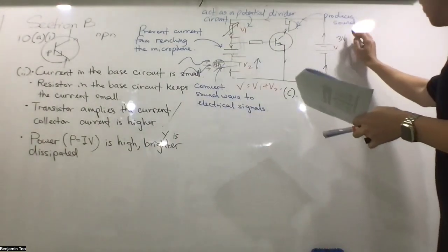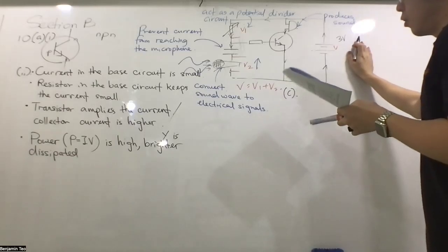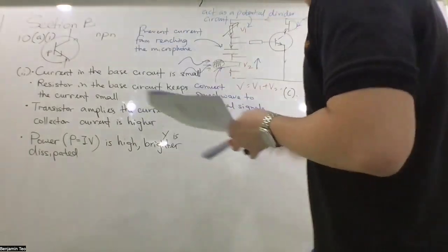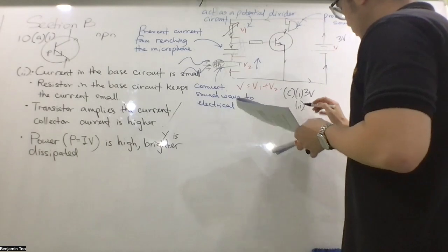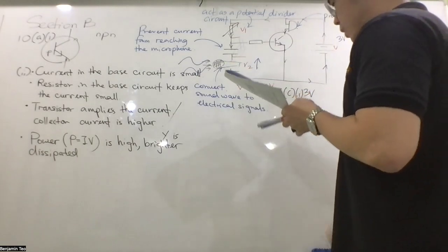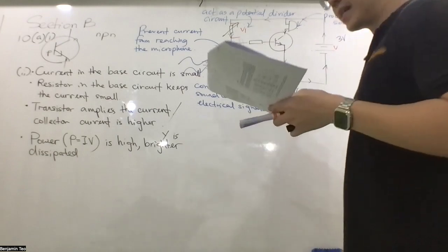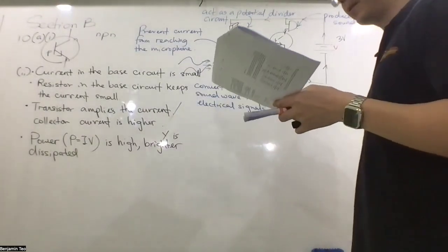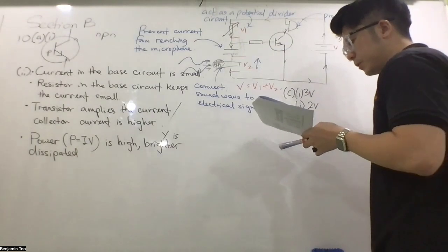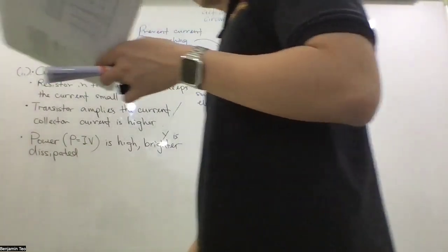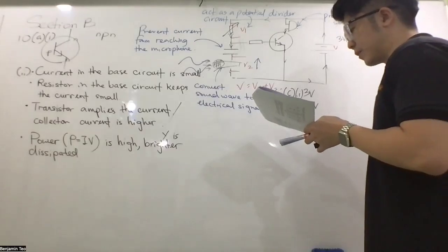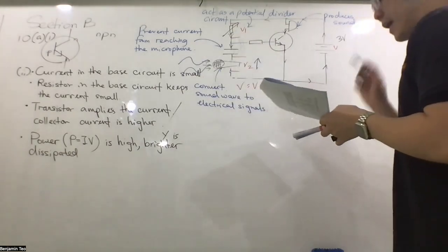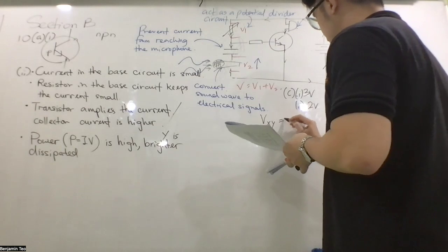The whole thing is 3 volts. So XZ is the whole thing also, that is the same, 3 volts. Potential difference across X, Y. So you know YZ is 1 volt. The other one should take the rest, 2 volts. And find the maximum resistance so that the bulb lights up. Maximum resistance of R. Okay, we already know YZ is 1 volt. So XY, VXY is 2 volts.